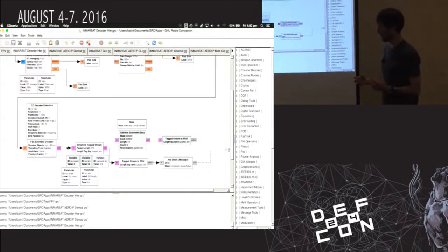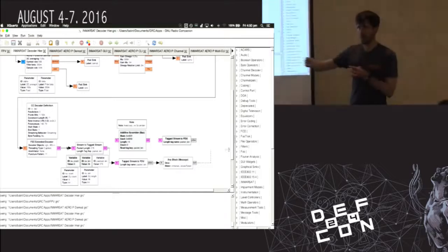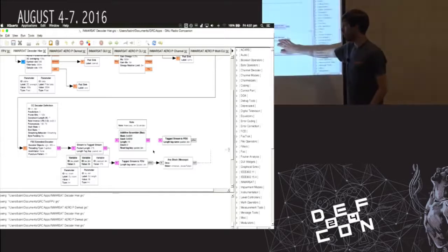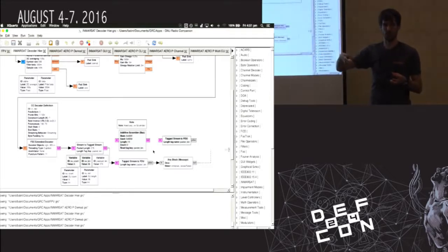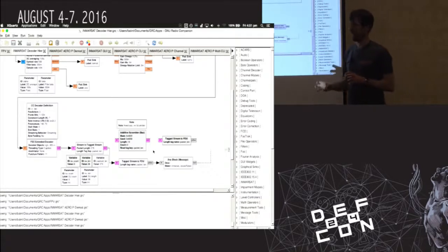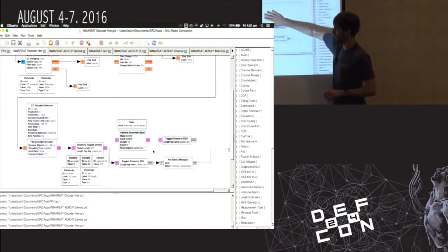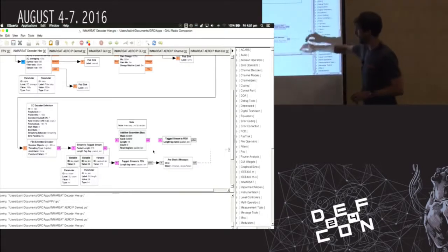So you saw before that you basically need to generate a scrambled stream. This block will do it too, but this block also internally checks the CRC. So once it descrambles it and makes sure it's a valid CRC, it then adds metadata to the message saying if it's valid or not. If I was to use this outside, I need to also implement another block to do the CRC checking separately. But at the moment, that's all being done in there.